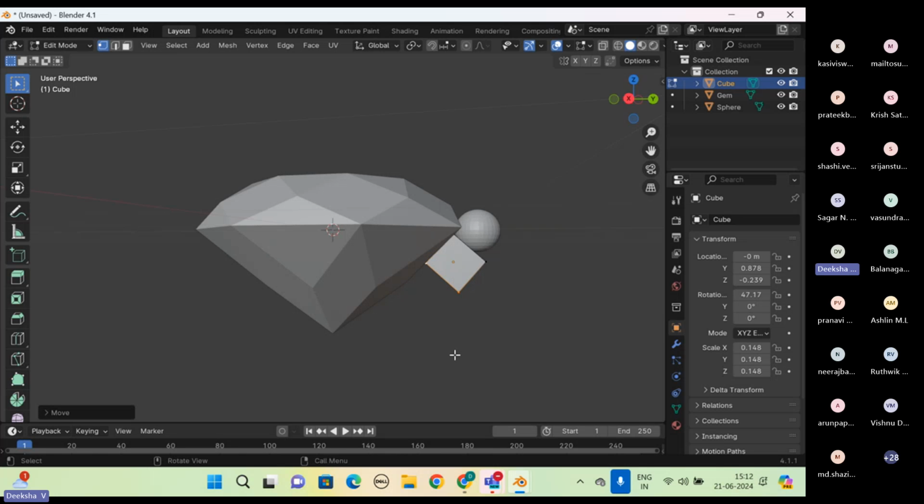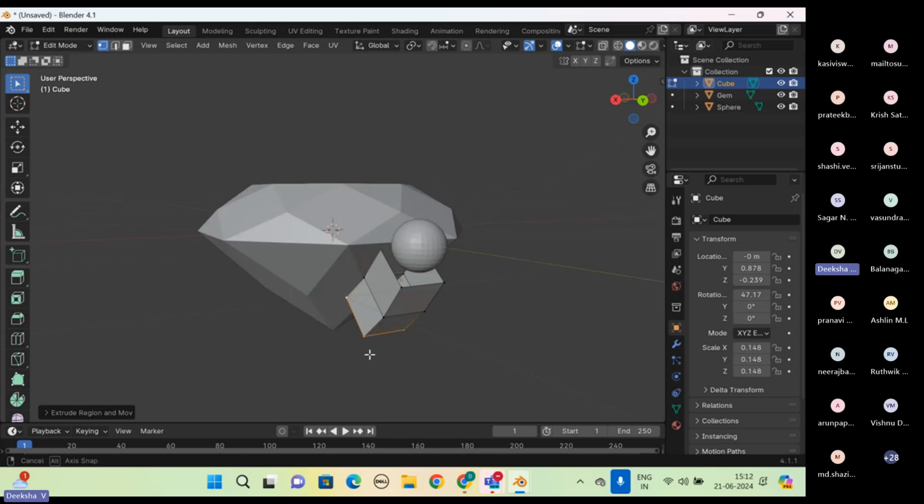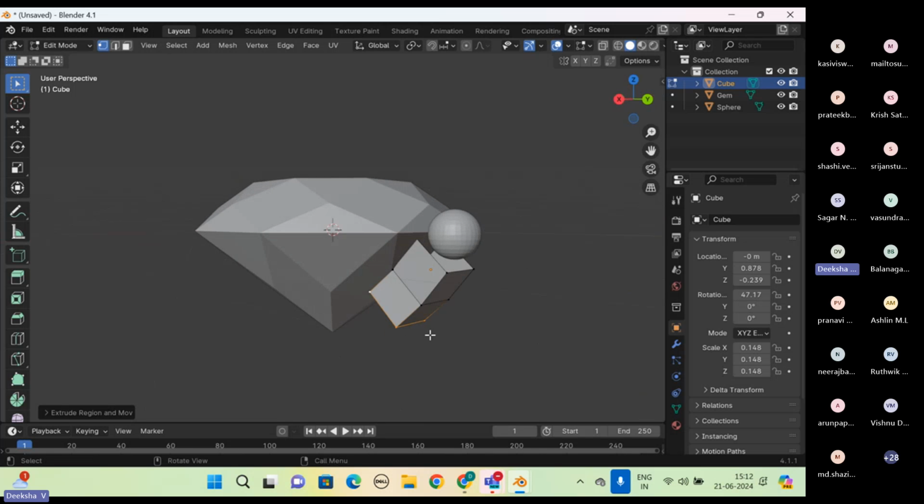And how do we delete the faces? So basically you will have to select your two faces. So I deleted the top and bottom face. So go to face select option, which is on your top side, or click on 3 shortcut. Select your one face, shift and select the other face. Once you've selected the two faces, just click on delete option on your keyboard or click on X. So then you'll get a bunch of options in that you can select on faces.